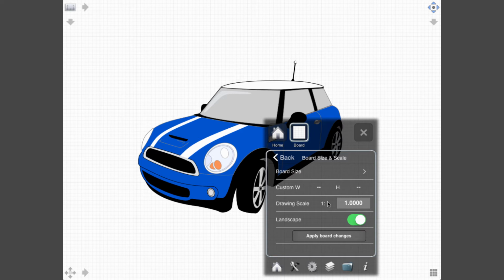Setting or changing the drawing scale will affect all the measurement related features of the coordinate system, display and input, but will not change the internal storage values. Values stored by iDesign internally will always be at scale 1.0.